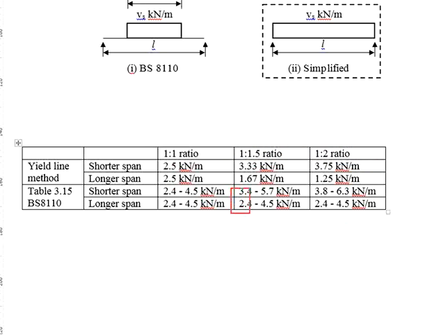The estimated loads, even the minimum loads, are always greater than what is estimated using the U-line method. Although the 1:1 aspect ratio is slightly smaller, the difference is within 0.1 kN per meter, which is relatively small. From here you will see the conservative measures adopted by the British Standard.